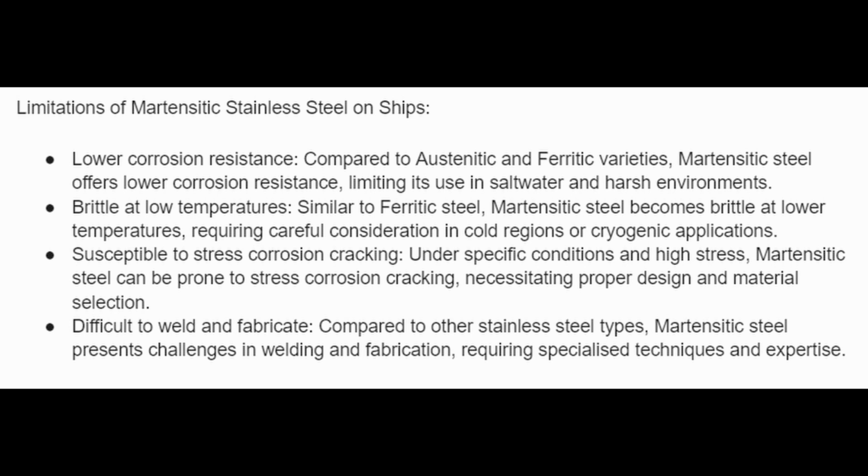It's susceptible to stress corrosion cracking. Under specific conditions and at high stress, martensitic steel can be more prone to stress corrosion cracking, necessitating proper design and material selection. It is also very difficult to weld and fabricate compared to other stainless steel types. Martensitic steel presents challenges in welding and fabrication, requiring specialized techniques and expertise.